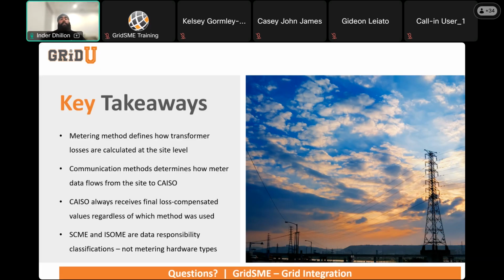So if you're having a paired resource containing a BESS and a BESS aux, the majority of the time you would initially have a BESS aux meter there, or an external signal whenever your BESS is idle would be sent to the BESS meter, so the BESS meter can stop recording the retail energy, and it'll all be billed to your BESS aux meter.